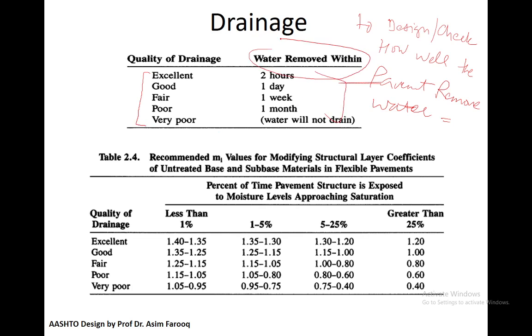As you can see here in the lower model, water under the pavement is one of the primary causes of pavement failure. Whether it comes from groundwater, rain, or snow, if the layer becomes saturated and weakened, that also contributes a large percentage, which could decrease the CBR value.